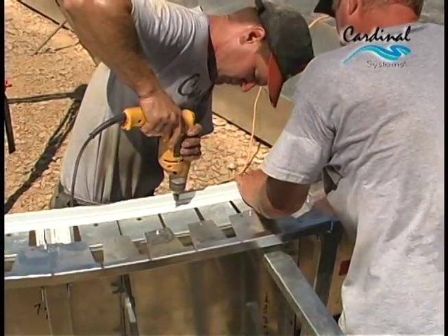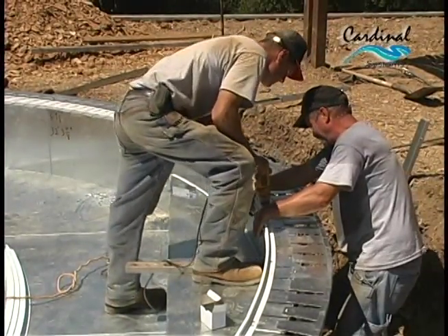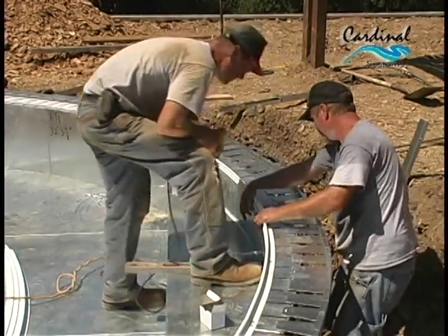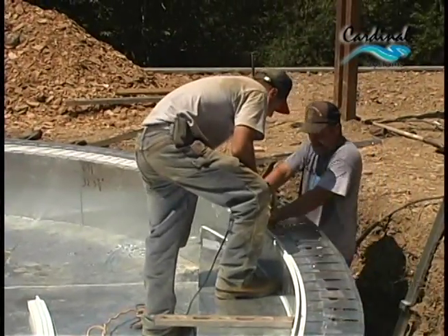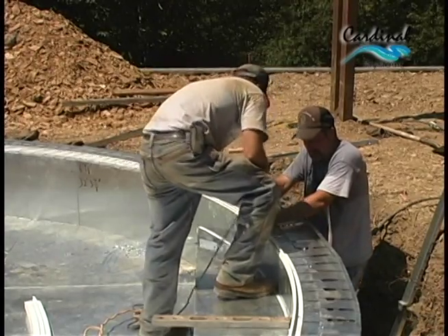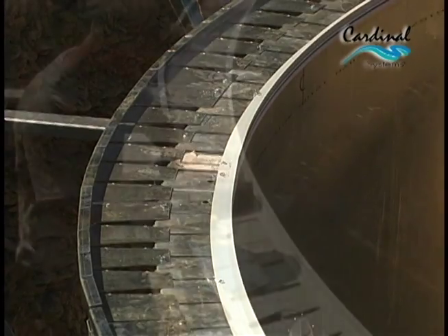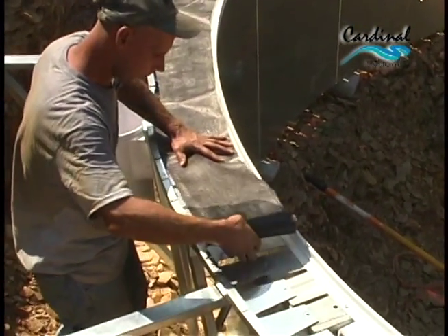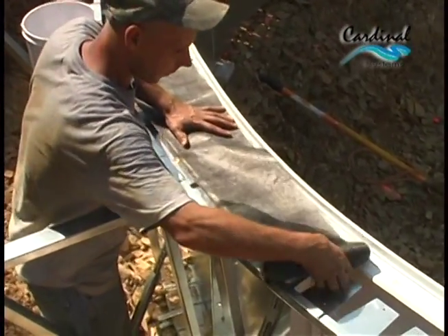This particular project calls for installation of cantilever coping with fiber optic track, special effects lighting for the outer perimeter of the pool. The coping is installed on the inner edge of the panels, with the bead receiver facing away from the pool. This coping accepts the liner bead and the fiber optics and is Tex screwed into place. Landscaping cloth is used to prevent the pea gravel concrete from oozing through the gaps in the stone coping support system.